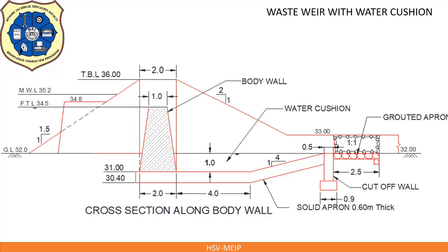Now let us draw upstream wing wall. Mark RL 34.80 and draw horizontal line up to the end of earthen bund. We can leave certain distance so that the balance portion can be protected by stone pitching, and also this portion of return wall embedded in the earth on both the sides, this side as well as another side,